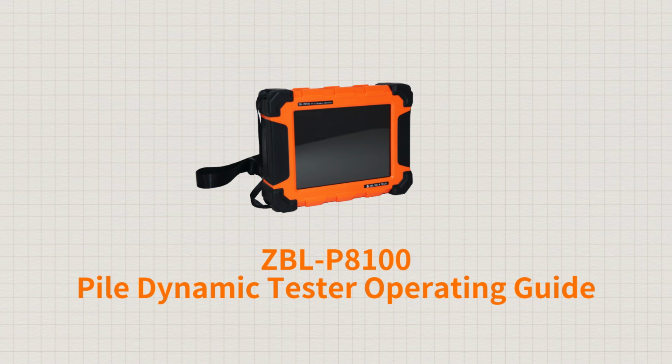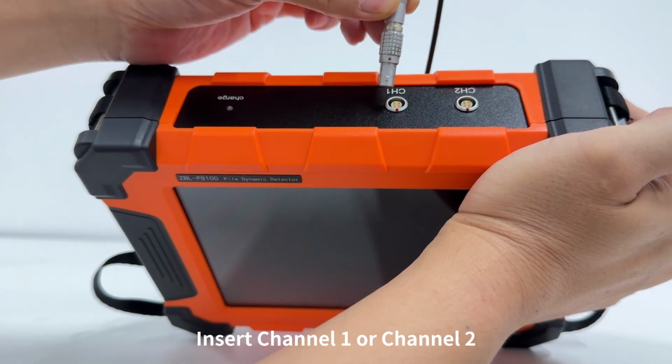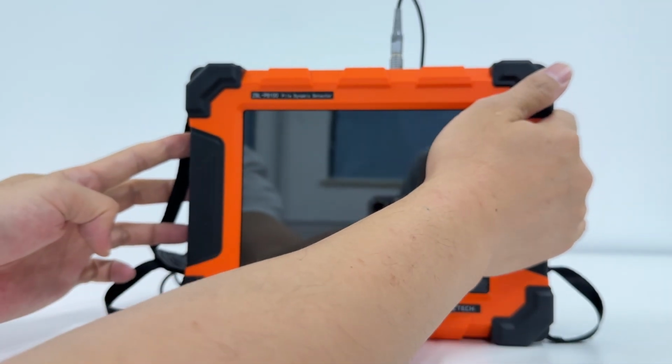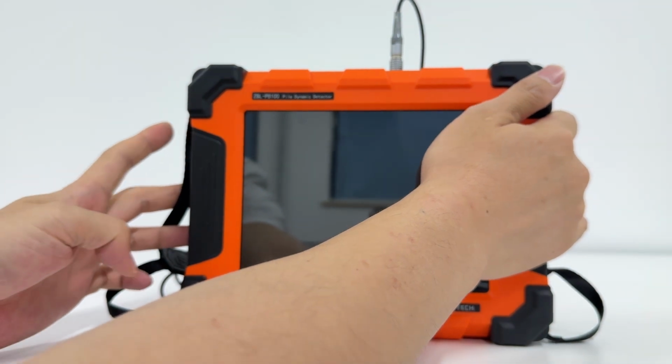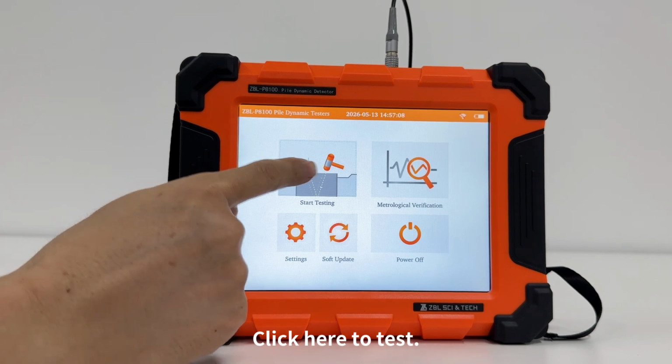Pile Dynamic Test Operating Guide. Align the red dot with the red channel dot and insert the sensor into channel 1 or channel 2. Long press for 3 seconds to turn on. Click here to test.